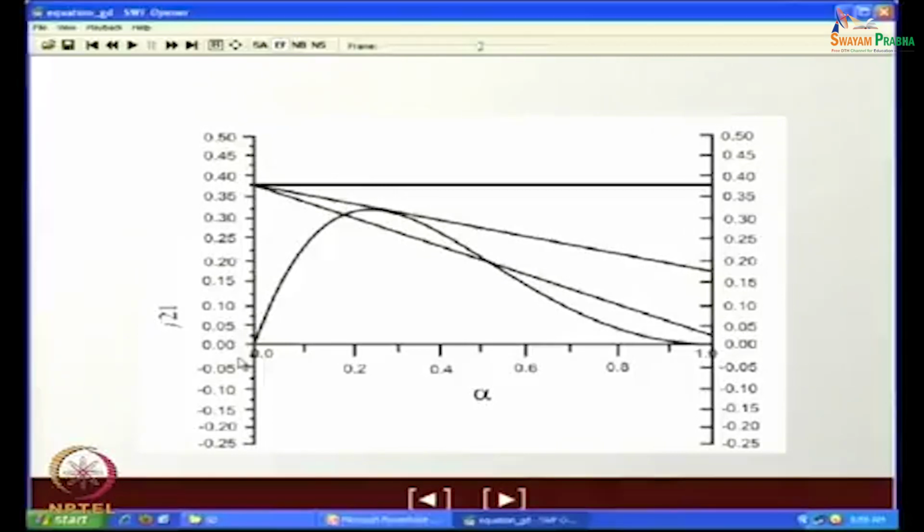So, for counter current flow with gas up, liquid down, we all know that it operates within a particular stable operating range, and that range is limited by the flooding condition at one end, the weeping condition at the other. Okay. Below the flooding point, we can get counter current operation under two conditions. One is at low alpha, the other is at high alpha. The point at lower void fraction denotes the bubbly flow situation. The point at higher void fraction denotes the droplet flow or maybe the wispy annulus sort of flow condition.